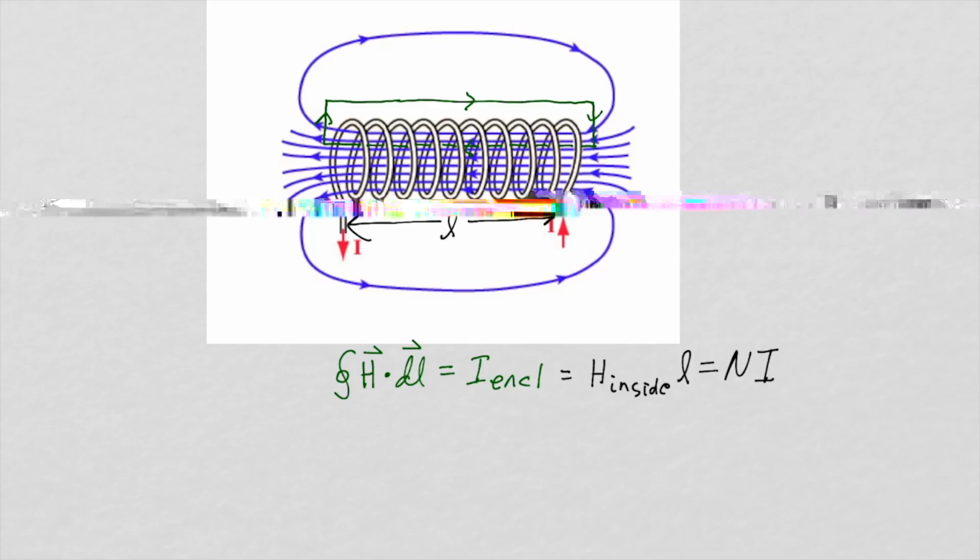And we have to use the right-hand rule when applying Ampere's circuit law. So we put the fingers of our right hand in the direction of integration. And when we do that, our thumb points into this surface defined by that path of integration, and the current is flowing in the direction of our right thumb. So in that case, the current enclosed is positive.